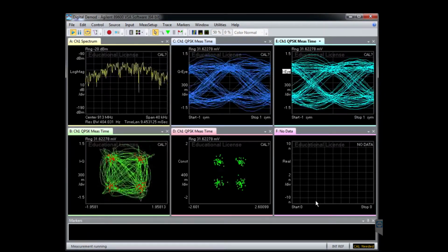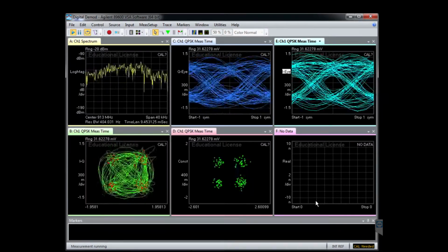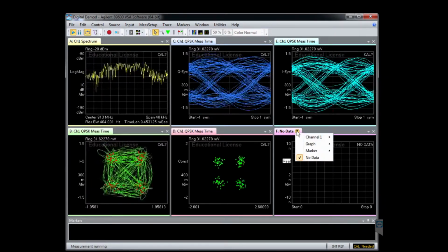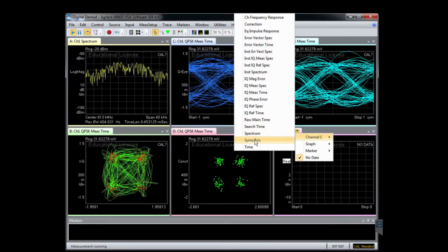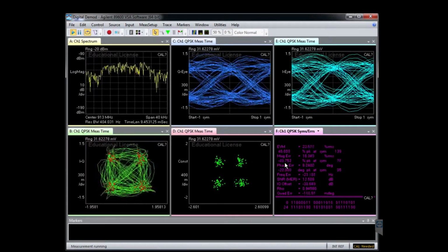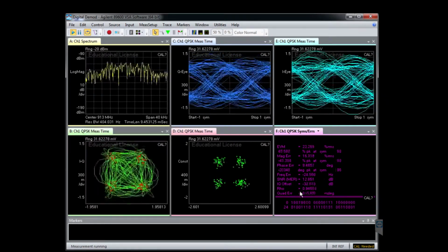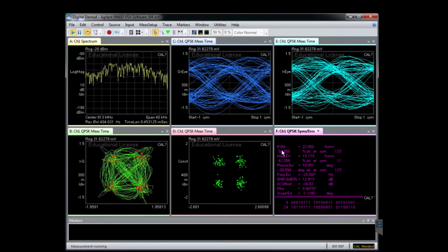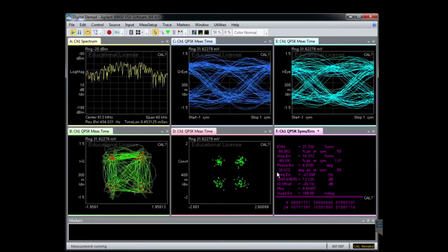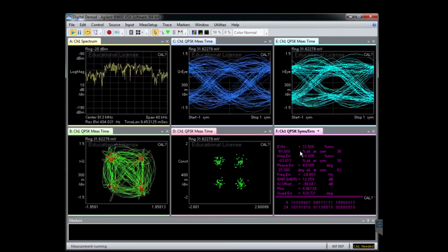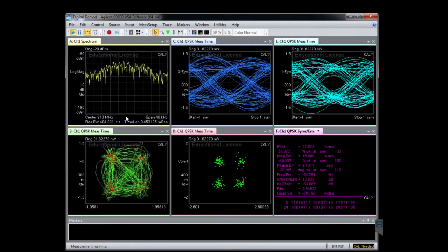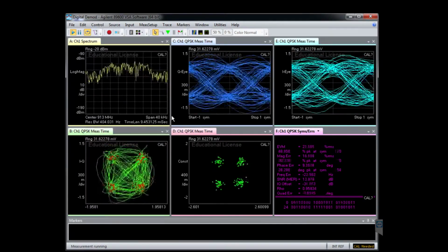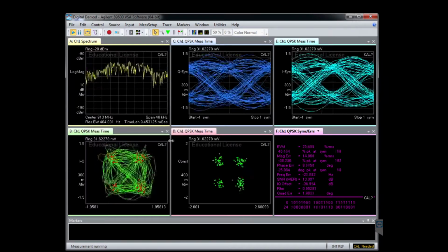And the last thing that we are required to set is the error statistics from the symbol error, which is here. In the statistics here, we can see different error rates, like the EVM, and also we have SNR as well, and other error statistics are also provided. So now we can adjust the power at the transmitter and see how these figures will be changing.